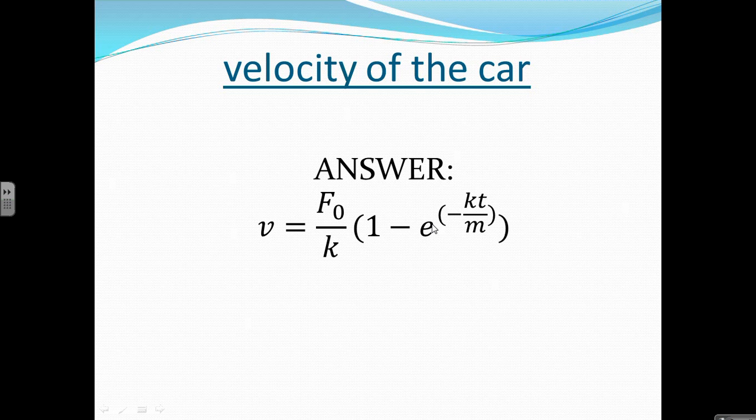We'll talk about this a little bit in class. I'll show you the individual steps, but I want to give you the answer so you can take it from there. If you are going to try this one, you have to replace your acceleration with dv/dt, split your variables between sides, then take the integral of each side, and go through the natural log. Please note that there is going to be one chain rule acting when you go through this equation.